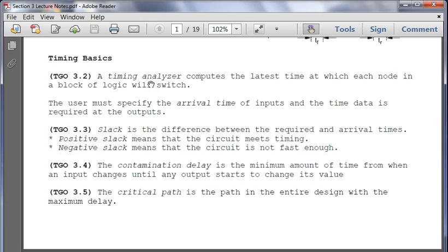In the ALU they designed, the critical path was 50 nanoseconds, and what I did was I had to put buffers that held all of the inputs to make sure that they all came out at 50 nanoseconds. And this is why, because if you don't, then all your contamination delays start going off. It affects power consumption, it affects circuit accuracy, it affects all kinds of issues.